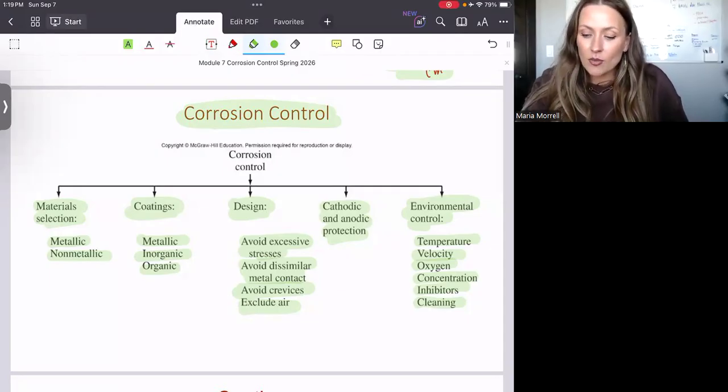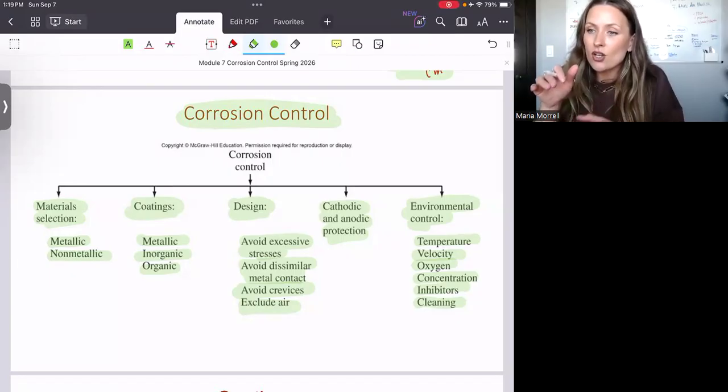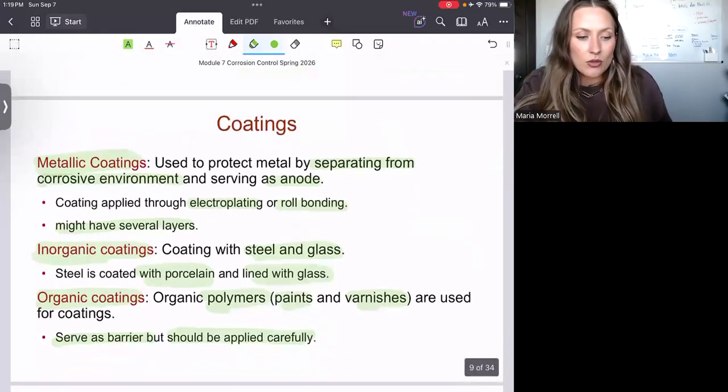So once again, because this dust, dirt, debris all creates a perfect, beautiful crevice corrosion, because the material underneath has a lack of oxygen. So you're looking at the oxygen gradient galvanic cell that, trust me, will work beautifully.